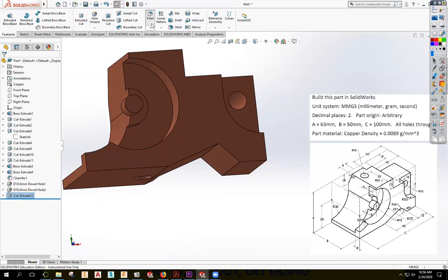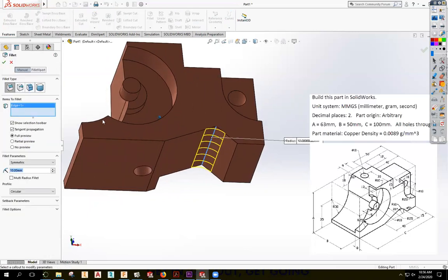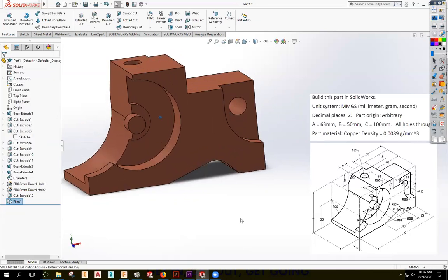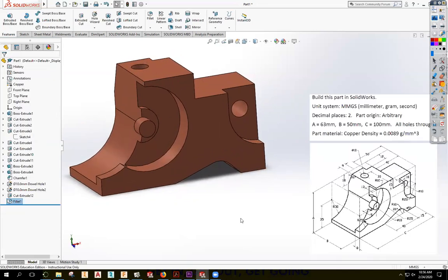And now add my fillet. Okay. Or if you don't know the center point, if the sketch doesn't include the center point of the fillet, draw a square. You can draw a square with a sharp corner, do that, and then add the fillet. Don't try and do the fillet in the sketch. That means you have one more object you have to worry about making tangent and all that stuff. Keep it simple. Questions?